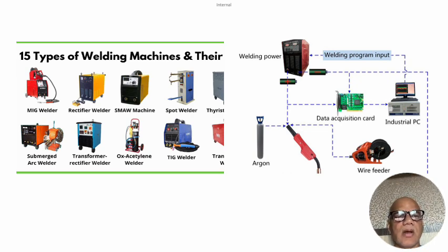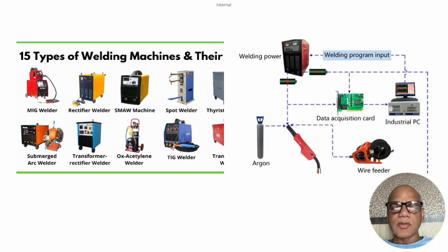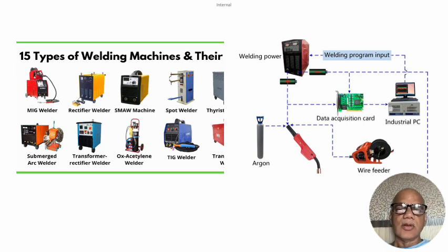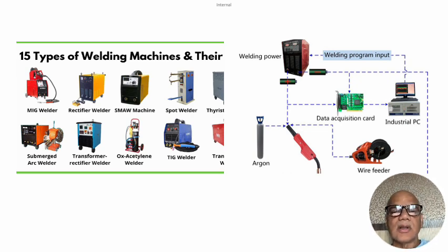But what happens is, in continuous wire, you need to adjust your arc length automatically, as you will be feeding the wire continuously, and very few machines offer the variation in the wire also, and it is difficult also for a welder to really select the wire feed and current separately. As you increase wire feed, current increases, or vice versa.